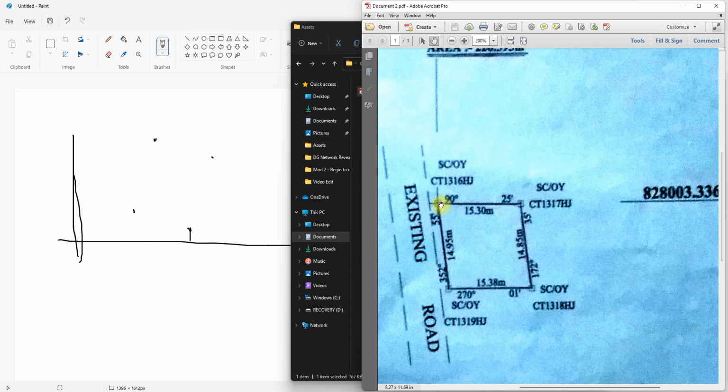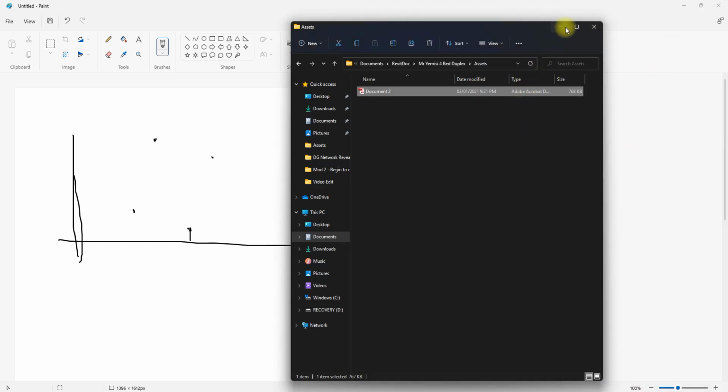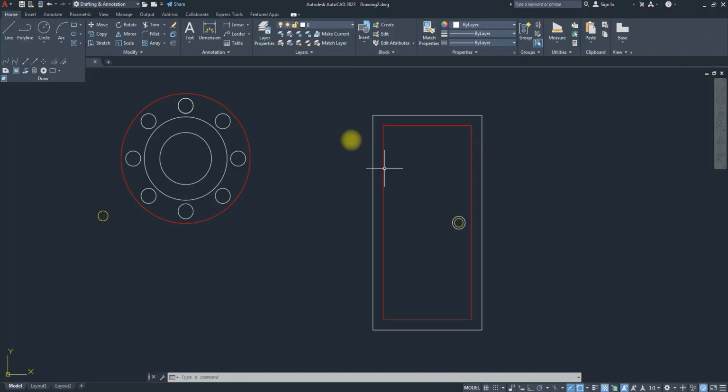So if you are able to snap to those points, you can just create your line, since you can utilize your snap to snap from here to here, click, and drop. So that's what multiple points are used for, just to snap to a particular location that you can use later in the future. That's the best way I think I can explain multiple points.